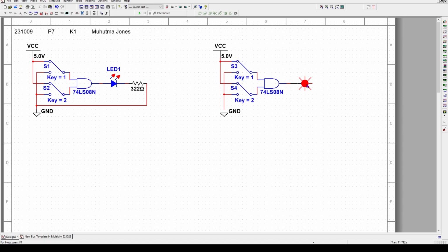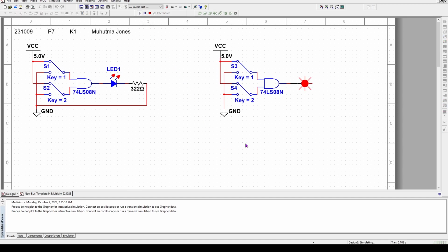So now we got this probe on here, and I'm going to go into video mode, and I'm going to use my 1 and 2 keys to say, look, they both work the same. The probe's easier to see. There's no resistor on there. Why isn't there a resistor on the probe? It's implied that the probe has a built-in resistor. How come it doesn't go back to ground? It's implied that the probe has a built-in ground. So that just cleans up the screen a little bit and makes it nicer.